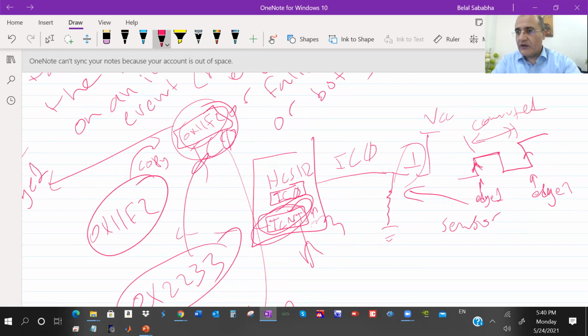Okay, and if it counted 1,000 times, and every count takes 1 millisecond, so this is 1,000 milliseconds, 1 second between the two rising edges. You can configure the event to happen on a falling edge if you want. That is, after the first time you receive the rising edge, you get interrupted, and the TCNT value is captured and saved in the input capture register.